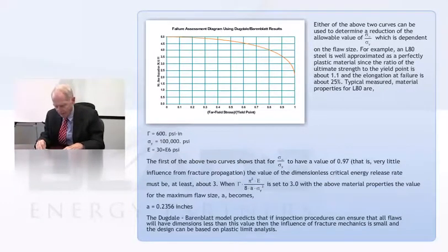Anyway, if you know anything about your flaws, you know your material properties, then this curve, which is really based on the Dugdale-Barenblatt solution, is going to relate the size of the cracks and the stresses that you can apply to the material.